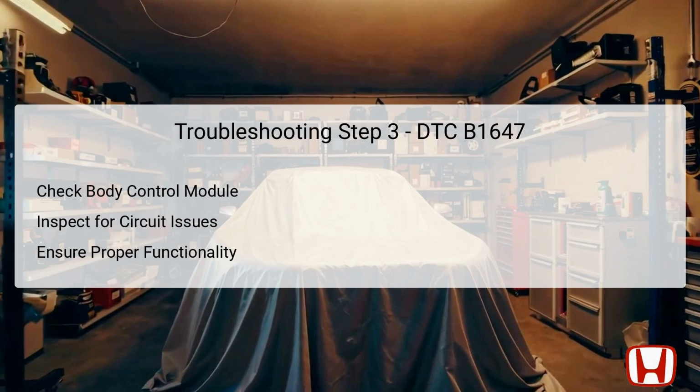If the voltage does not meet specifications, it could indicate an internal failure of the body control module itself, which may require replacement. The diagnostics for the body control module may include tests for proper voltage input and output, ensuring that the module is functioning correctly and is free of internal circuit issues.